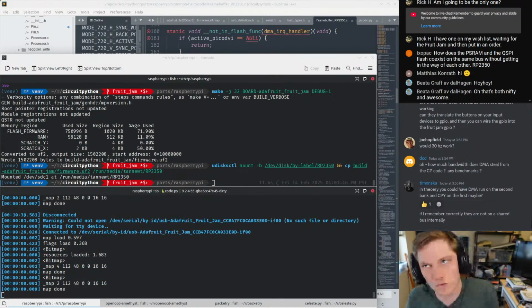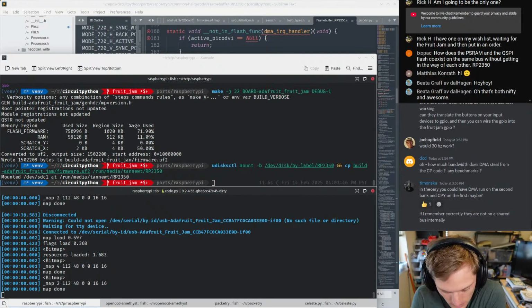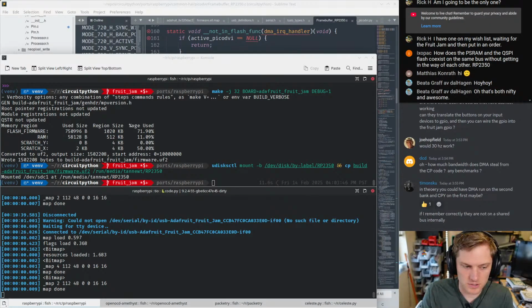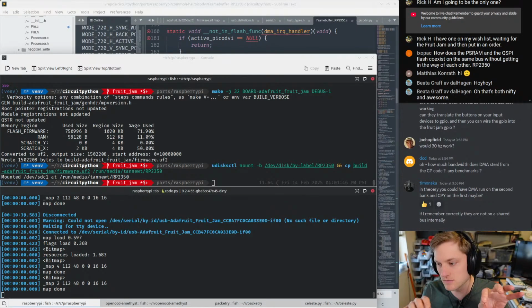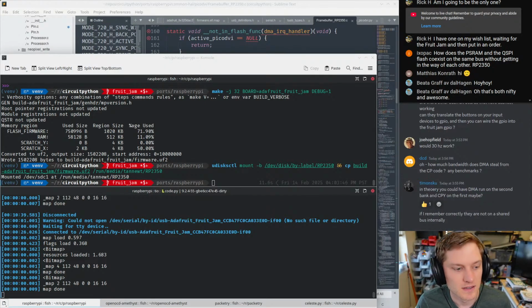We could quad 8. So this uses the trick that when you do a sub 32-bit transfer, it mirrors the remaining bits to the other parts of the 32-bit word. So if you do an 8-bit DMA transfer, the 32 bits ends up with 4 copies of the 8 bits.